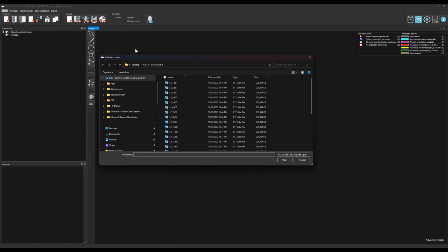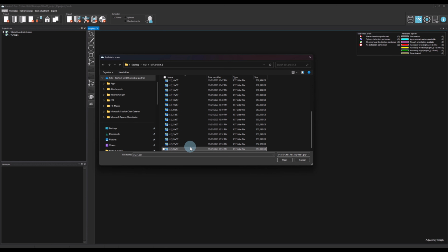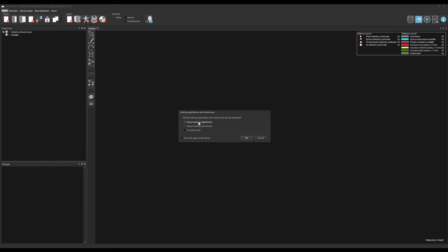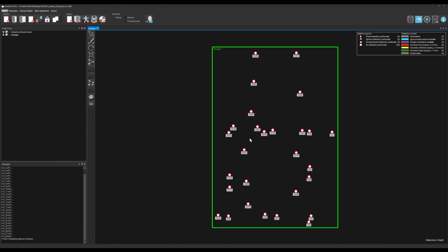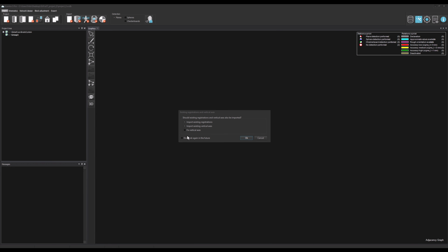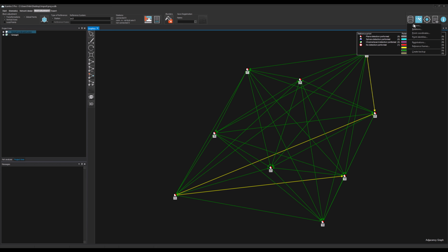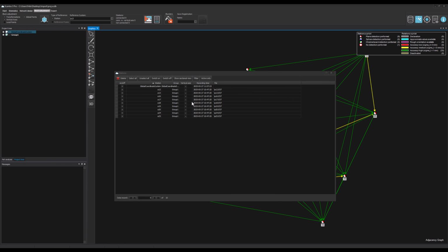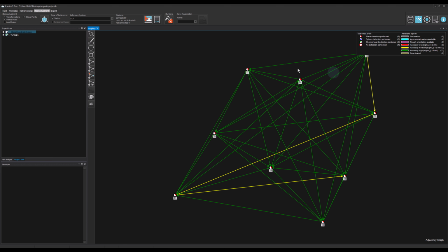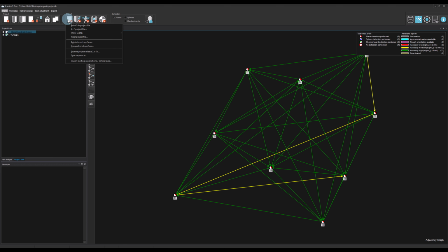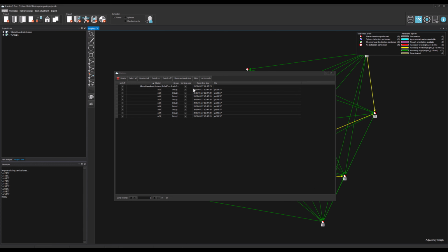Pre-orientations can originate from registrations of other software or from scanners with integrated sensors such as GNSS sensors, inertial measurement units, or compasses. Note that the option Fix Vertical Axes is a special case for E57 files and has to be used if the vertical readings were already applied to the point clouds, yielding leveled scans. The reason for this option is that E57 does not explicitly store vertical readings, for instance, from a compensator. Hence, Scantra cannot distinguish cases where no vertical readings are given or if rotations about the X and Y axes were already applied.